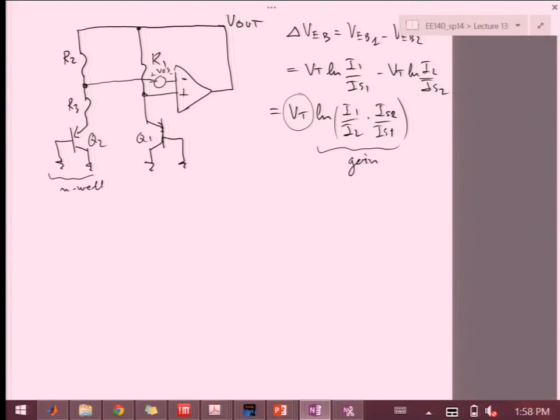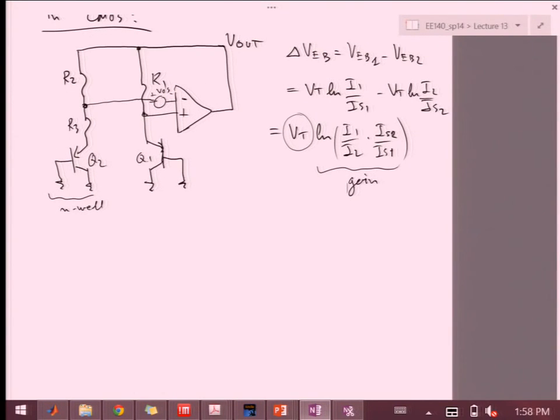generator, now let's see how we can solve exactly for the V out. So first thing, we're going to look at this VR2 and VR3. So we're going to say that VR2 is R2 over R3, VR3, because there's no current flowing here. So same current is flowing through both.